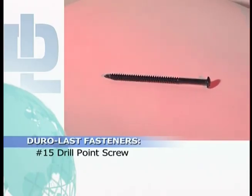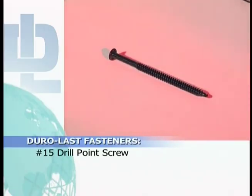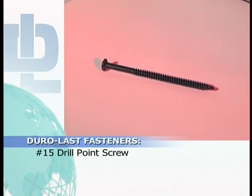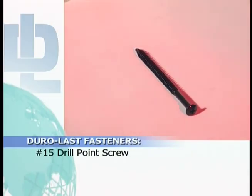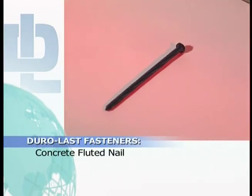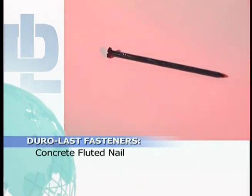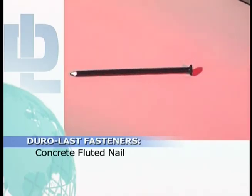The Duro-Last number 15 drill point screw is also identified by its single flute cutting edge, drill point, and a P3 driving head, the same as the Duro-Last number 14 drill point screw. However, on decks with a lighter pullout value, such as thinner gauge metal decks, this larger gauge fastener can produce higher pull test results than the number 14 screw. The Duro-Last concrete fluted nail is used on structural concrete decks and is hammered in place. It requires a pre-drilled 3/16 to 7/32 pilot hole, a minimum 1.5 inch depth, to achieve a minimum 1 inch penetration into the deck. Be cautious to ensure that you select the proper length fastener.